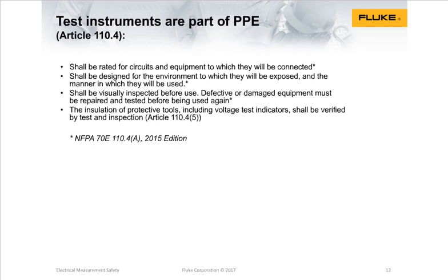In many cases, I've seen where you come on the job site and your meter may be broken, you may have forgotten it, something may have happened to it, so you borrow someone else's piece of test gear. You want to be qualified to understand the operation of the test gear and also how to inspect it to make sure that it's fully operational. If you're doing a dead live test on an active conductor after you have performed a lockout tagout, you want to make sure that you're using a piece of test gear that gives you the correct results and you can interpret those as working in a safe environment. We'll talk a little bit about that.